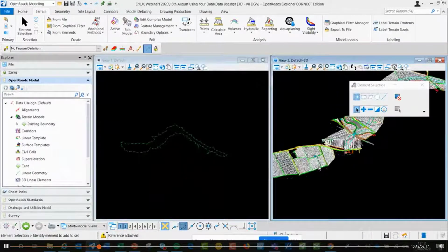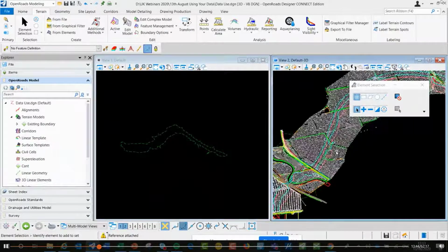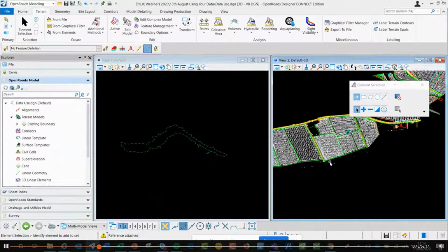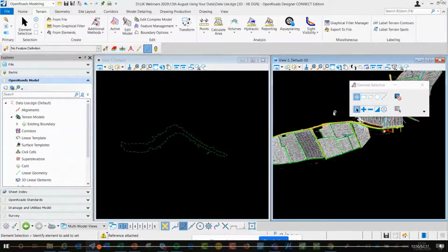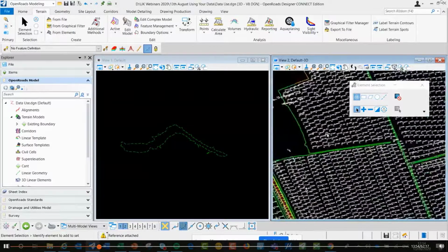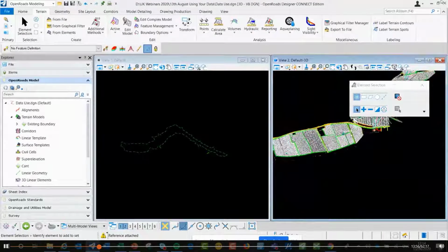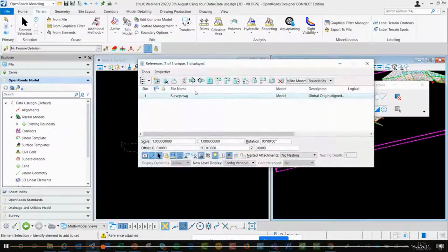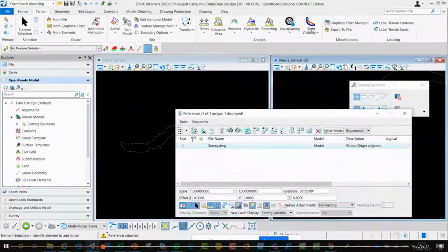I've got it. The 3D file was active, but as you can see, I've referenced it in here, and we've got a proper 3D, and all the referenced information is snappable and attributable, so you can work with this quite well by referencing it in. The advantage is once you want to see more detail, you can just turn the reference off, and it turns off really quickly.